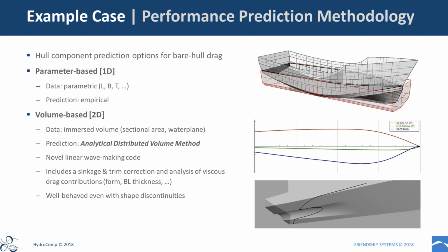But if you have a really tight constraint on a value like displacement, then of course there is also the possibility of keeping it exactly fixed. And we have also some special methods in CAESES where you can make sure that when you're doing changes to certain parts of the hull, you do some post-processing on the hull that readjusts the displacement to a fixed value, for example.